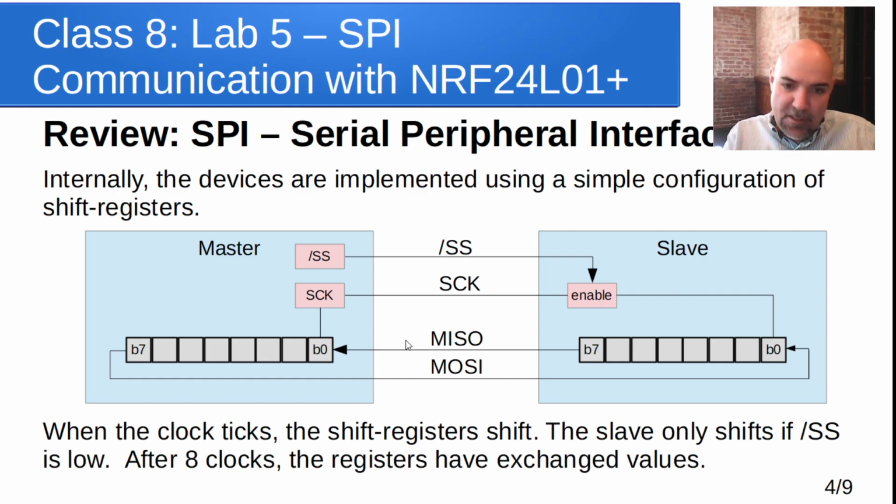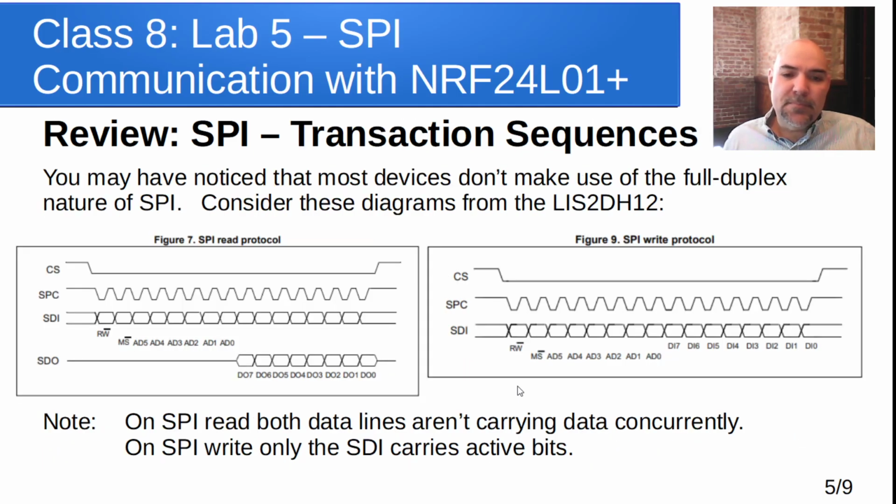We tick the clock, shift in whatever was on MISO into the least significant bit of some other byte, and then shift everything over by 1, and repeat it 8 times inside of a for loop. And once we're done with that, we will have the ability to talk to that device, and we'll look at the data sheet for how to do that.